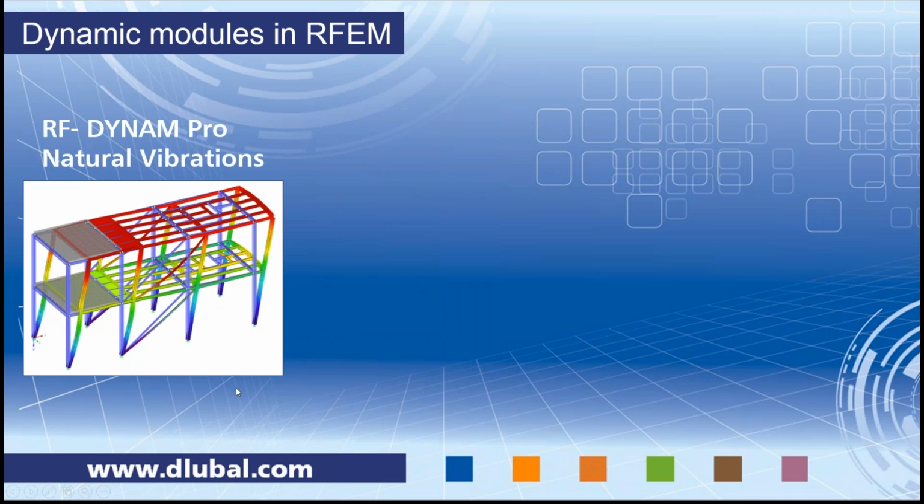This is what you always need, and it performs an analysis of frequency and mode shapes for members, surfaces and solid models. You can directly import masses from load cases. You can build combinations of masses in so-called mass combinations, and you can import stiffness modifications, axial forces, failing or deactivated members, or stiffnesses from RF-CONCRETE as initial conditions. So these are just a few examples. We have 4 eigenvalue solvers available, which I explain more in detail when we go through the example.